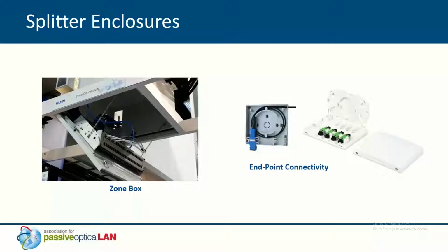So fire rating for air spaces requires plenum. Plenum means that if the materials in there self-extinguish, they won't reignite, and they have lower smoke than traditional materials. The reason we want that is because the air space above the raised ceilings is an air space, and if we ever had any issue, you don't want all those toxic fumes and smoke and reigniting fires going into the ceiling.